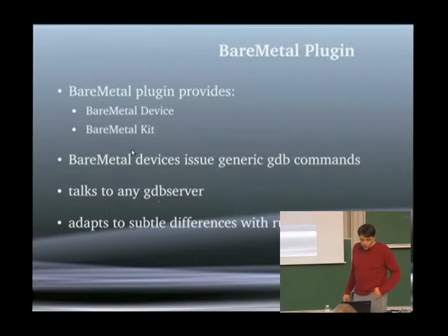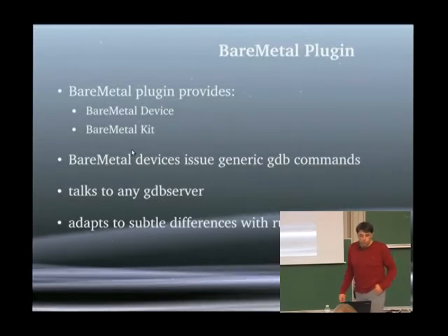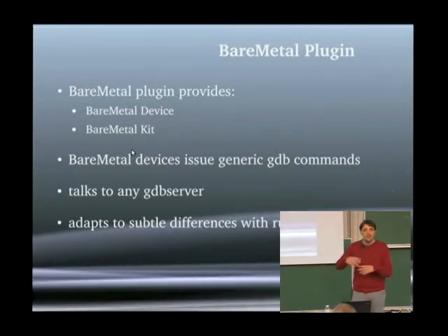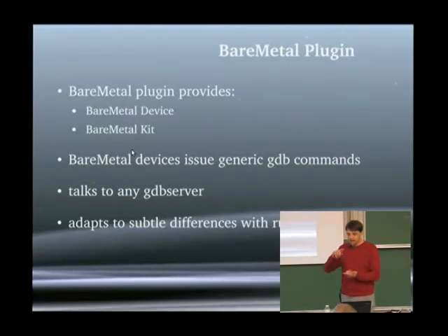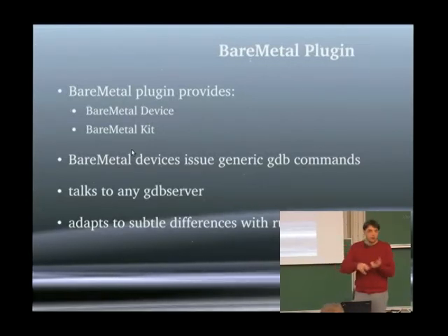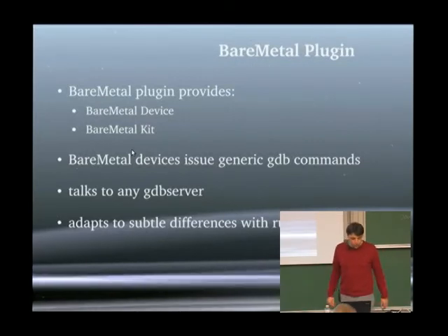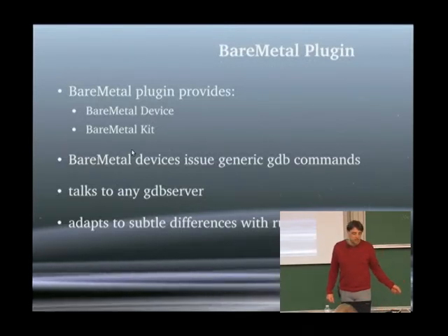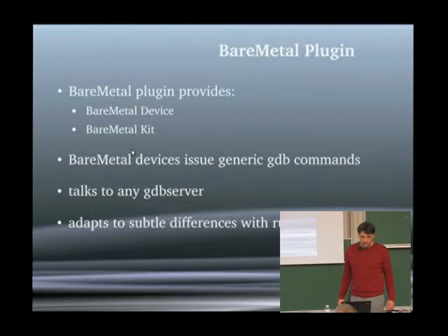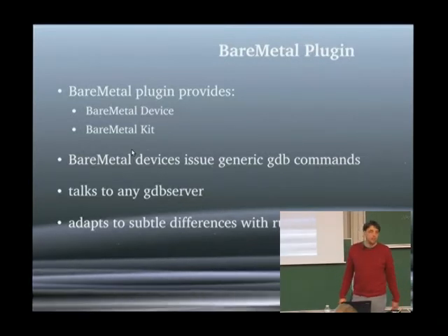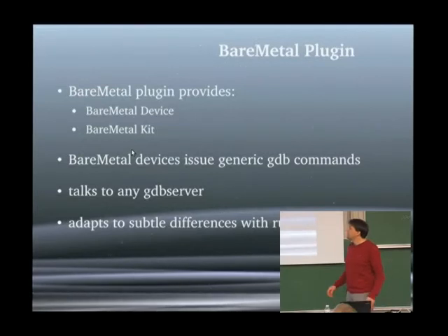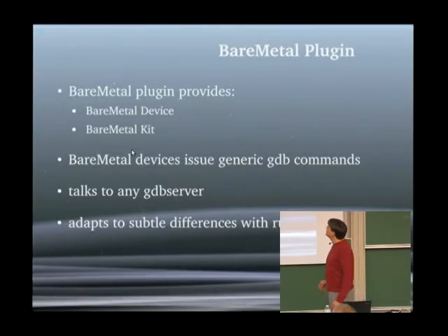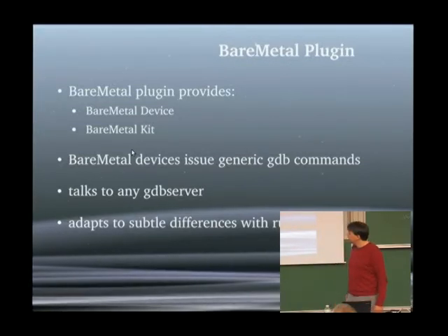Yeah, one thing that was missing to QtCreator was the bare metal stuff. So it has had nearly everything in place: the compiler support, debugger support, nice code completion. But one thing that was missing was that it was not able to directly talk to a hardware GDB server, which has some subtle differences in the way it has to be talked to. And that's why I wrote the BareMetal plugin for QtCreator.